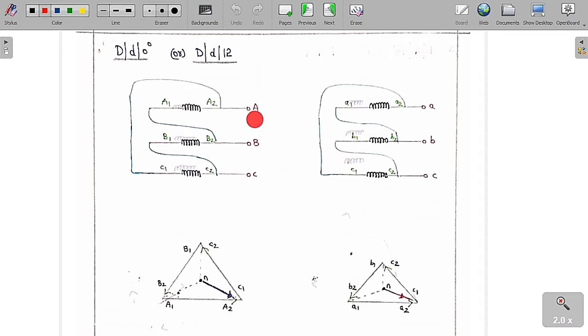And we are going to take the supply from A2, B2 and C2, so keep the arrows at the points A2, B2 and C2. So this is the way we are going to get it. These are basically line voltages, so we need a phase voltage. Phase voltage means take a neutral point in the middle and join a line from this neutral point to one of these vector points, which is A2. So draw the line, and we are going to get it in this fashion.